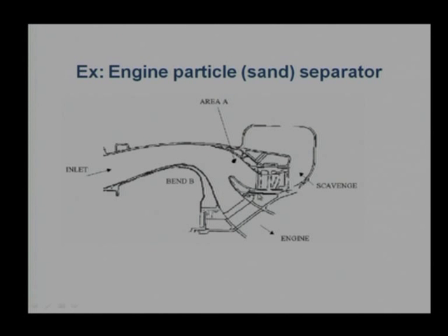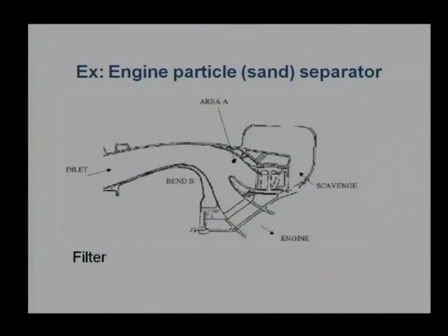If the particles are coming and hitting the engine cylinder or combustion chamber, naturally there will be a lot of problems in engine operation. It can fail anytime. However, there are system designs where we use redundant engines, so that even if one engine fails, other engine parts or other cylinders are working properly. That redundant design is possible, but can we reduce this wear rate by changing the system design? There is a possibility. We can think about changing the filter.